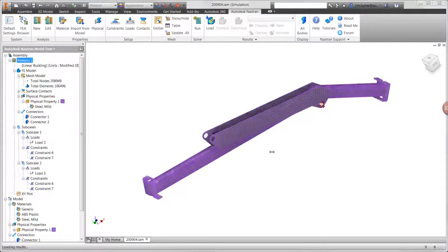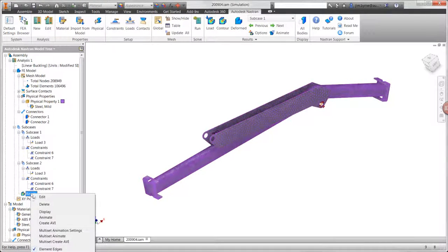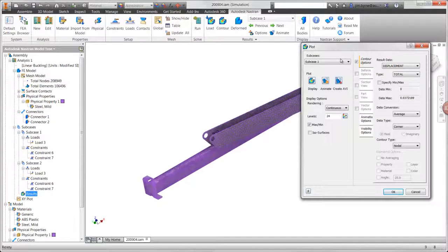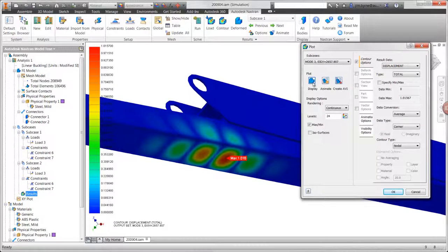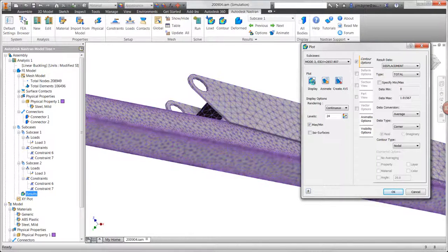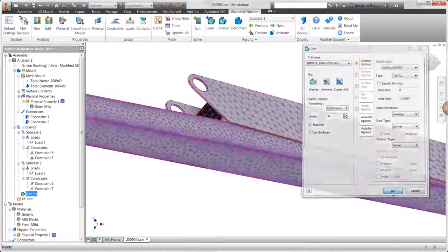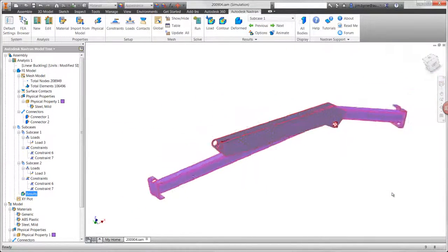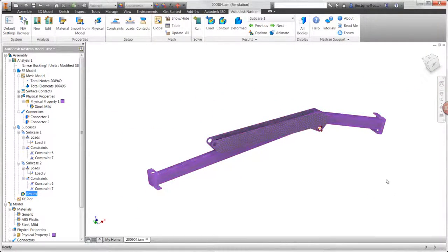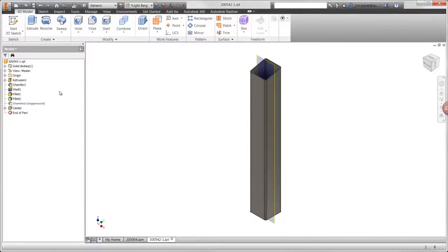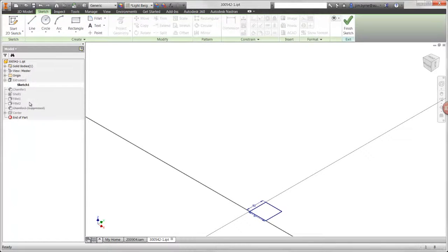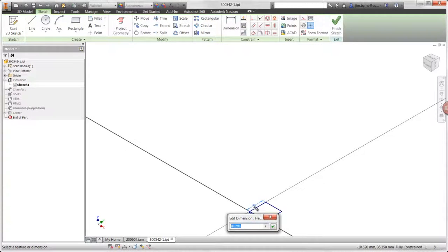The solver is sped up during this video, which takes about 4 minutes to solve for this assembly. Remember, the values for each mode will provide a buckling load factor. The first one we're observing is showing a load of just over 2,600 newtons. We may want to make modifications to the model dimensions to avoid catastrophic failure for larger loading conditions. We'll make the changes right here in Autodesk Inventor. The new design will be reanalyzed in Autodesk Nastran without the need to leave the CAD system.